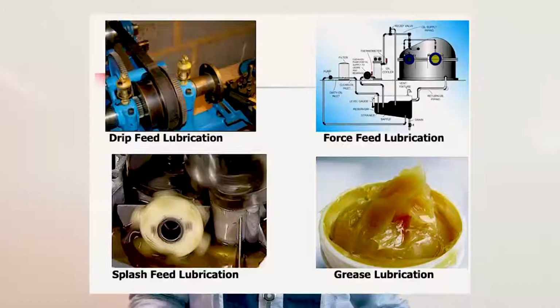The third one is the oil force feed lubrication. Here you use pumps to forcefully send your oil to the point of application, and then it is ejected on the surfaces. And of course, there's also an arrangement for recycling where every oil that is used is collected and returned back to your reservoir, from where your pumping action can ensure that it goes back again to the point of use. And so it continues to circulate.